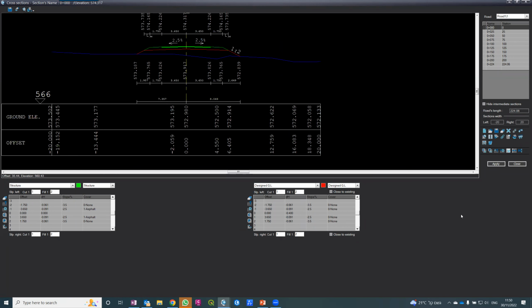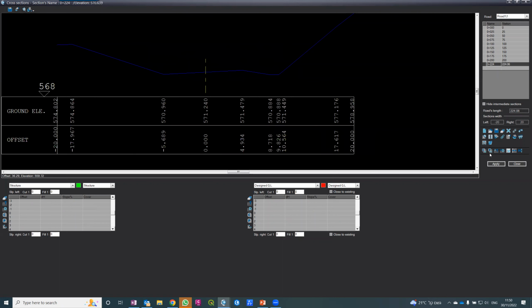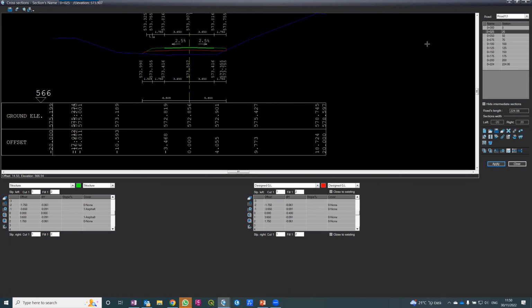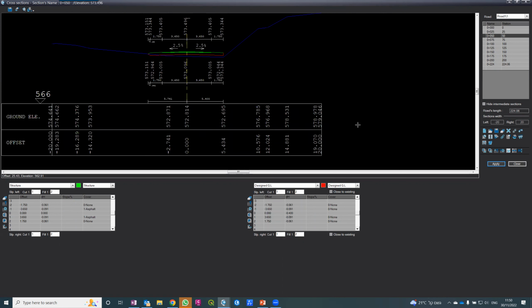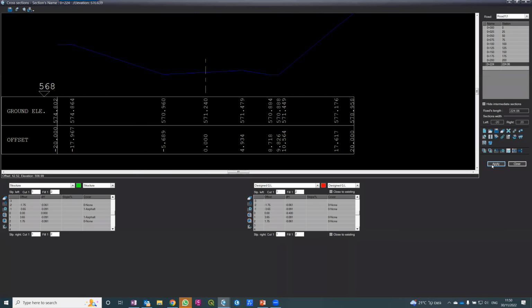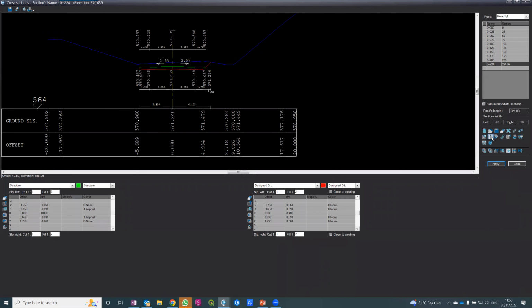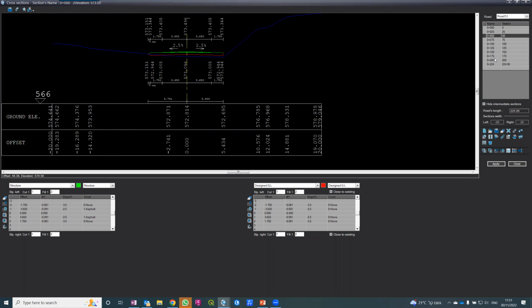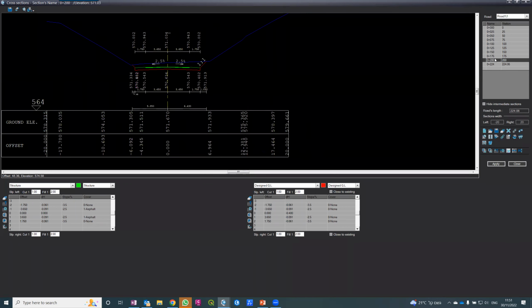I'm taking this section, go to the last. So if I take this section, this template, I can go to the next section and project it and get the next one and continue like this. But of course, this is not the solution that we want because it's an endless solution. So what I'm going to do, I'm going to use this template, go to the last section, paste it, and tell the software to do automatic interpolation. Okay, so if I go now, the software used this template and created the cross sections all along the road.